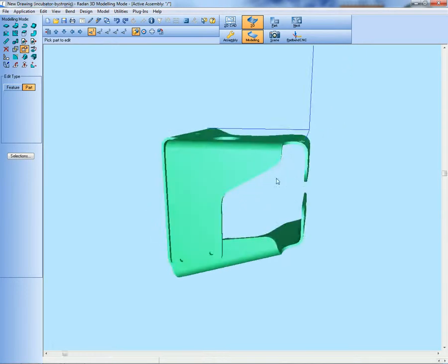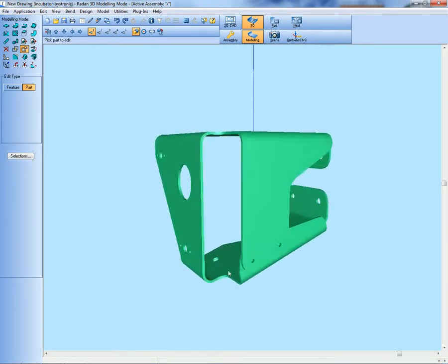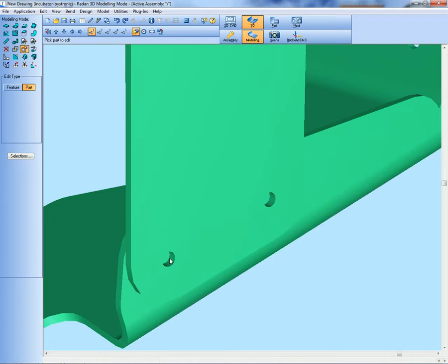We might also want to modify the part. So this is designed to be flood welded in there. Okay, we're not going to do that. We've asked if we could put a rivet in there. Does it need to be that strong? And they're happy for a rivet to go in there.